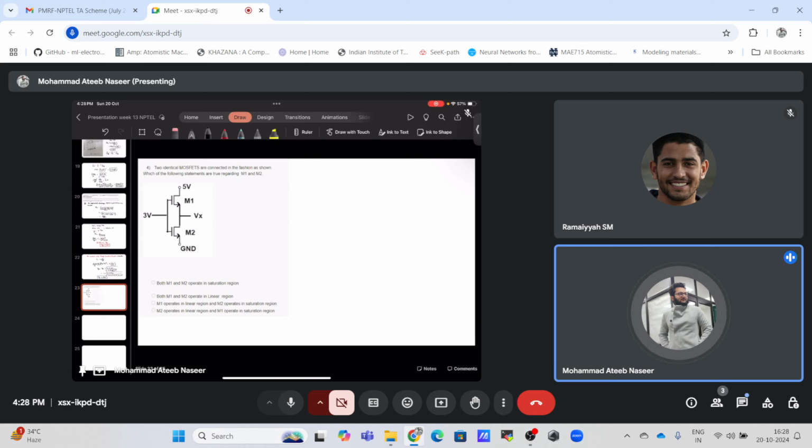Considering futuristic devices, sometimes you get very high leakages, and the current just saturates at a point, for example 10 to the power of minus 5 microamps per micrometer, and it remains constant from, let's say, 0.1 volt to 0.3 volts. So this can also happen. That region we can say is cut off completely, but in broader terms we will say it is the non-saturation region.